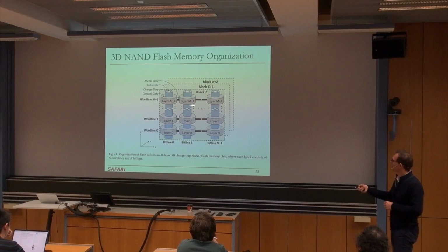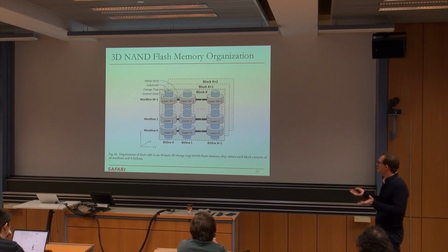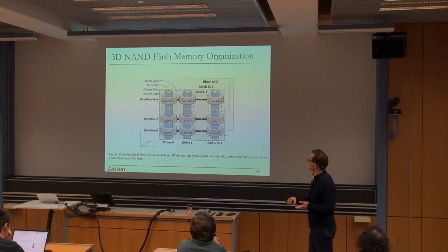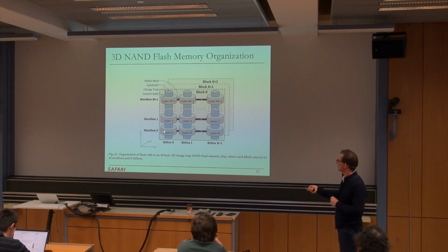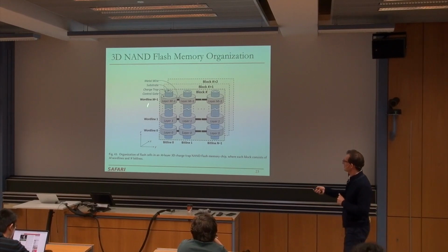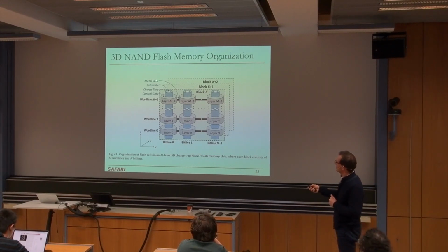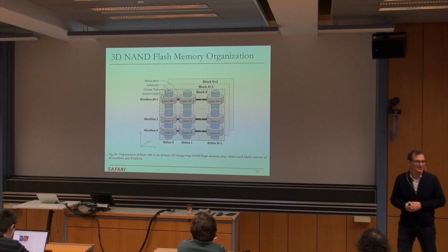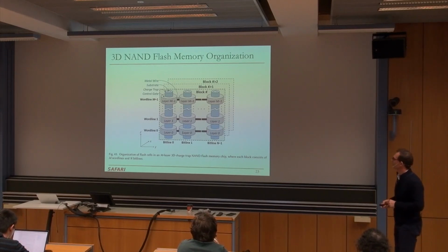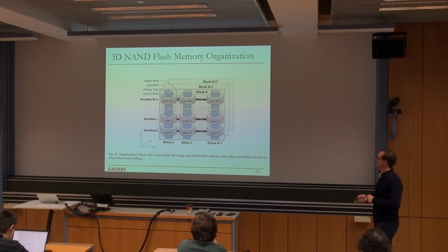This is basically, it's nothing different from any memory that we examined, except it's three-dimensional, right? This is the three-dimensional bit line. It goes across, and this is the word line that cuts the bit line. And your blocks look like this now. Your blocks are essentially three-dimensional, if you will. And this is the other block, and this is the other block, right? And you have the sense amplifiers at the bottom. Make sense? Okay, add another layer, of course, that's a sense amplifier layer.